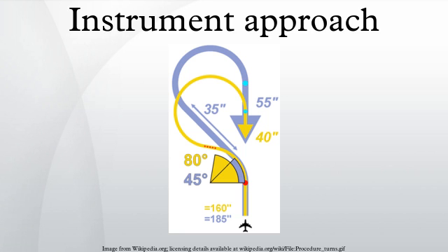A pilot may accept a visual approach clearance as soon as the pilot has the destination airport in sight. According to ICAO Doc 4444, it is enough for a pilot to see the terrain to accept a visual approach. The point is that if a pilot is familiar with the terrain in the vicinity of the airfield, he/she may easily find the way to the airport having the surface in sight. ATC must ensure that weather conditions at the airport are above certain minima before issuing the clearance.